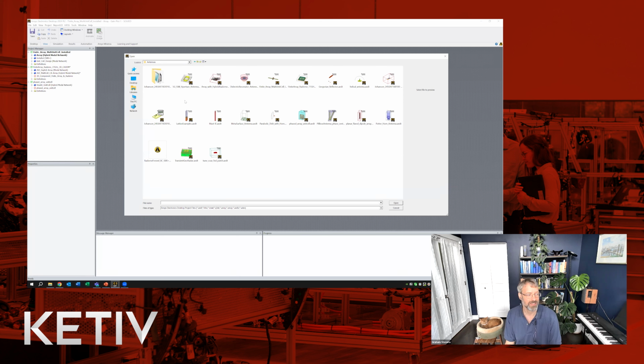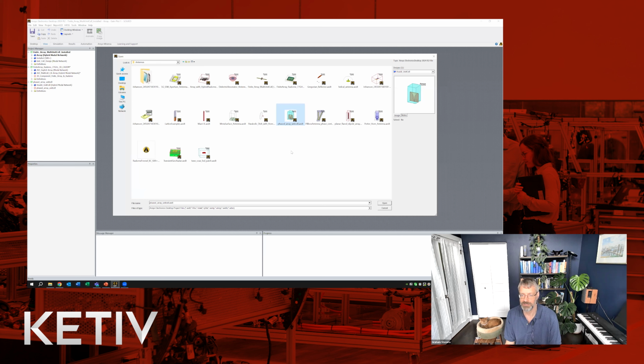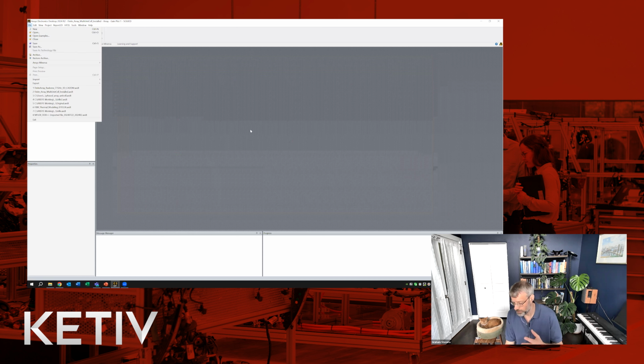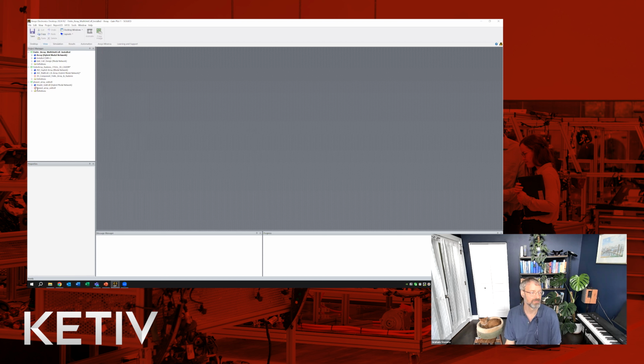So I've picked the phased array unit cell example here. I've picked the finite array multi-unit cell installed here and the finite array radome as well. Each of these examples are readily available within HFSS. You just open this up. You'll typically do a save as once it's open, and you save it to a disk space area that's a working area that you have access to, and then open up these examples.